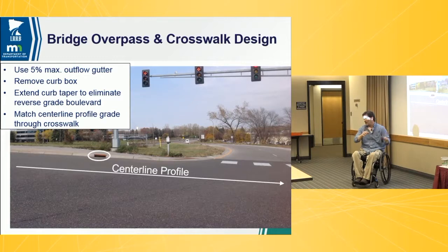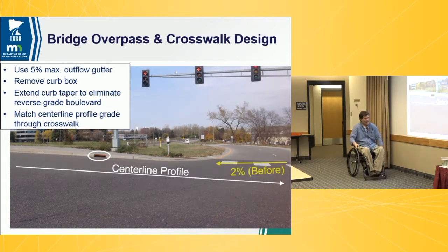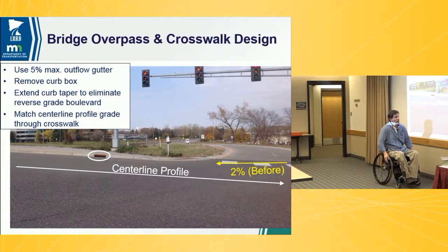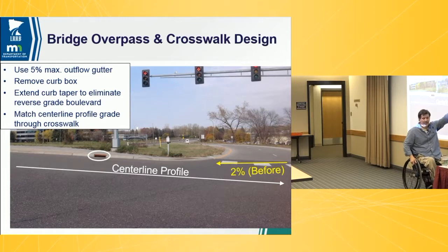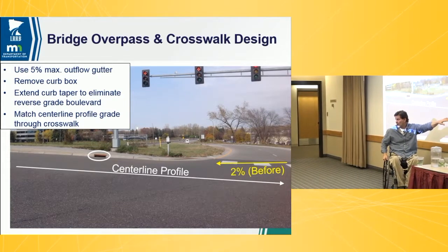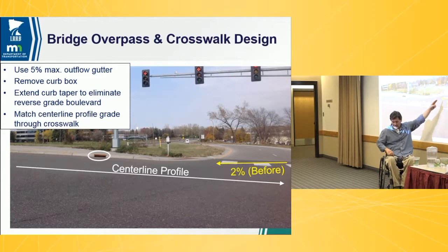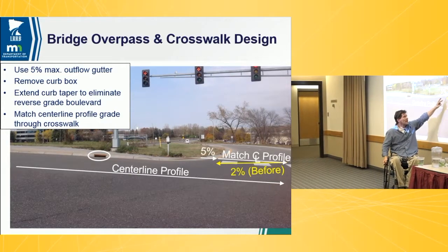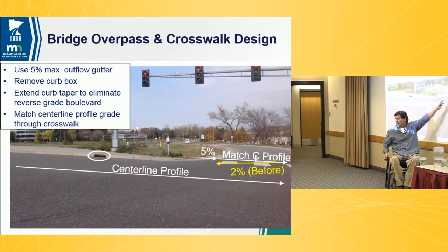But how we design roads and how we analyze these things and design them can really add extra complications. Especially when we want to take a typical section for this side road and have, for example, a 2% crown. Whenever I hold that 2% crown, which is going against the downward flow here, I'm lowering this point. So I'm making that much worse. So I'm losing grade right there. So that's where my curb ramp starts.